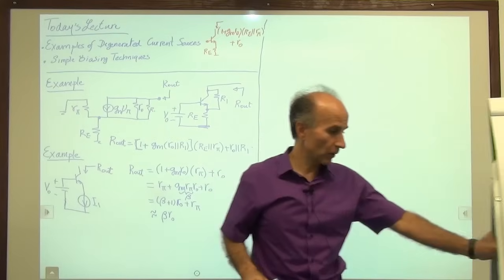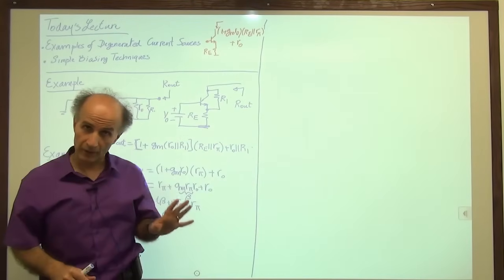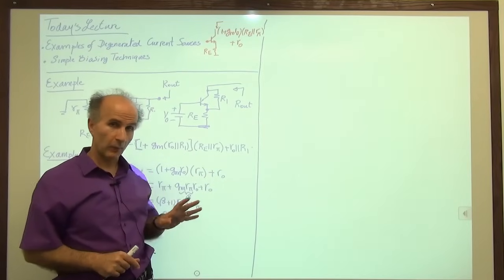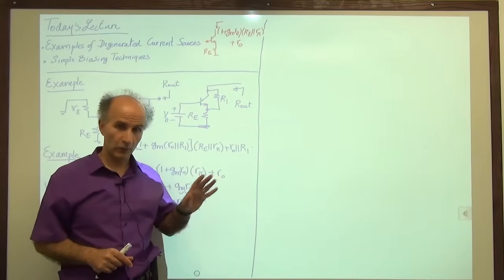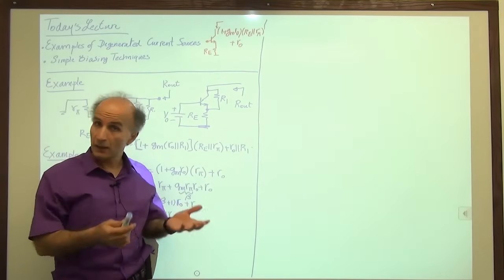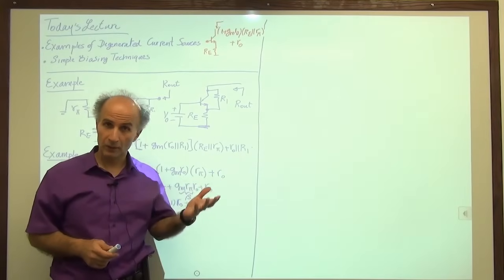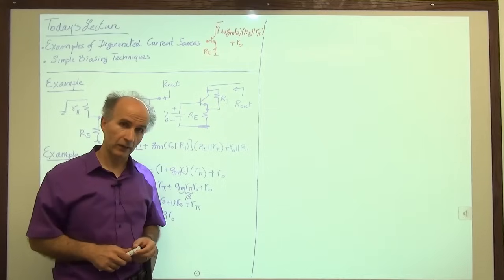So from now on in this course, if we have an amplifier, a common emitter stage with degeneration, we automatically assume that the early voltage is infinite so that we don't have to worry about early effect. Is that a realistic assumption? In many cases, yes. But if in an engineering problem you realize it's not, you can always quickly sit down and derive the results.